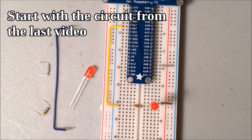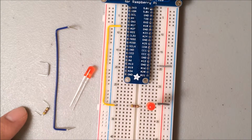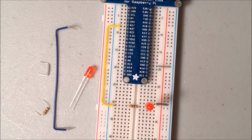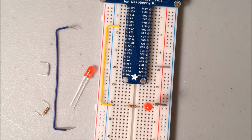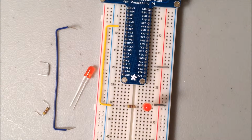We're ready to expand this circuit to make it a little more interesting, and we're going to do that by adding another LED, another resistor, this is a 470 ohm, and some more wires. So basically what we're doing is building another one of these little connections with an LED and a resistor connected to a GPIO pin.